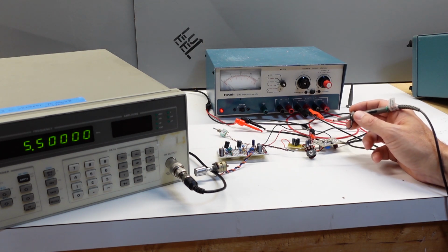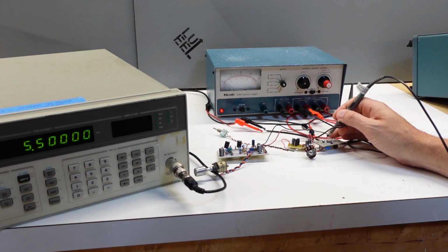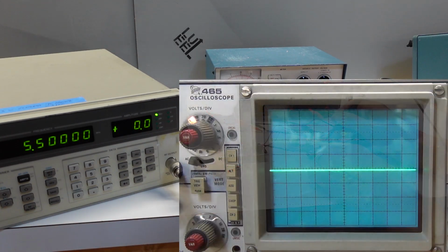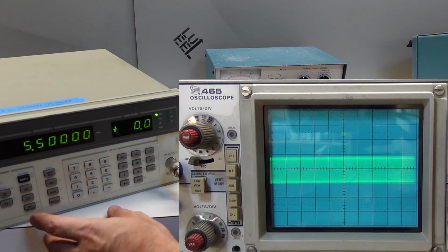Now as far as the target, again, I want to get to 300 to 500 millivolts peak to peak, so my minimum would be 150 millivolts peak. So that's 3 divisions minimum I want to see here. So let's see, when I turn on the generator, I'm starting out at 0 dBm. I'll get the probe onto the spot on the circuit, and that's definitely not 3 divisions.